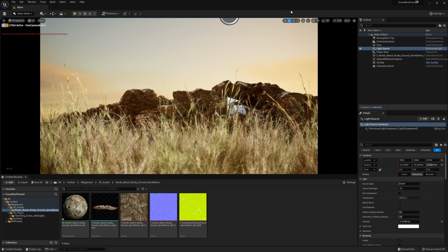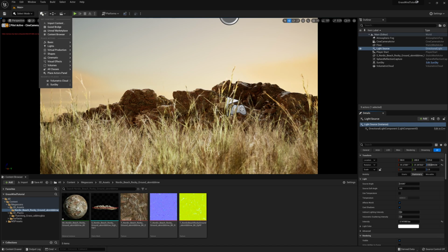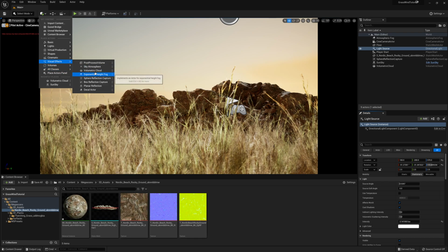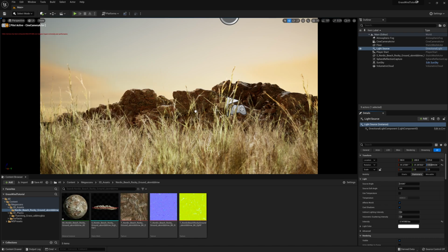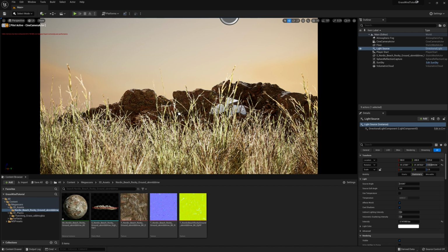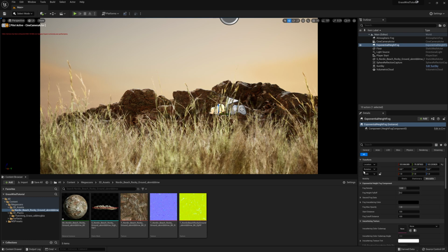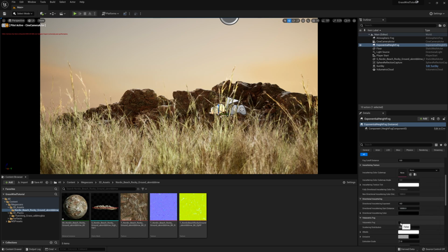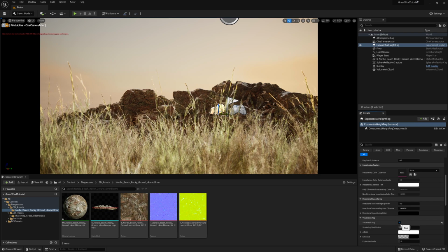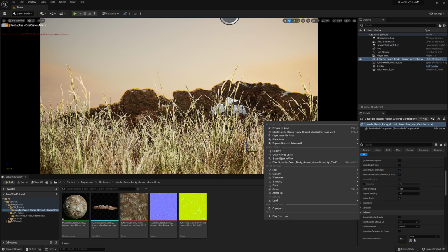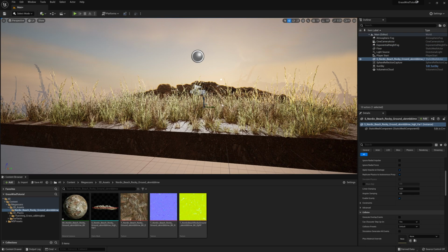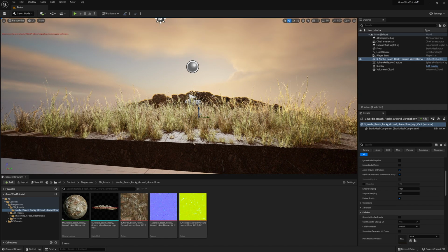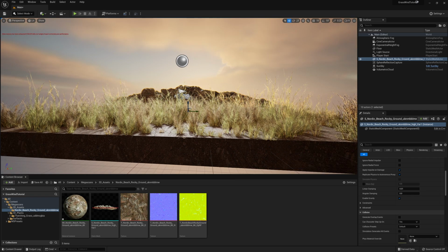If you want a little bit more here, you could go to visual effects and drop in an exponential height fog, and that'll give you some atmospheric fog in the scene. What you want to do is click on volumetric fog, and if we go out from our camera and eject there, you can see we've got this big gradient of a sky now.